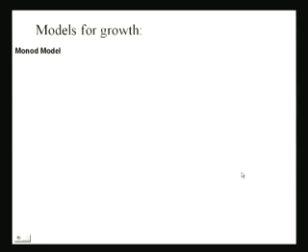So the Monod growth model, you're aware of the Monod growth model. dX/dt is mu X, where mu is given as mu max times S over Ks plus S. Okay. Now let me ask you this: is this equation that I wrote for the Monod growth model valid for all kinds of reactors?